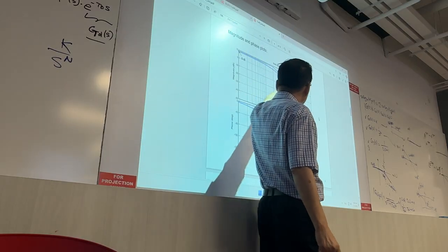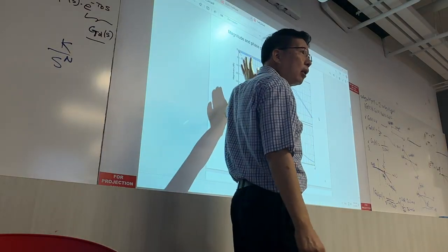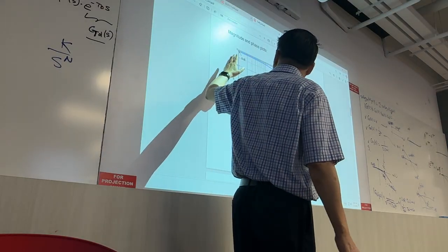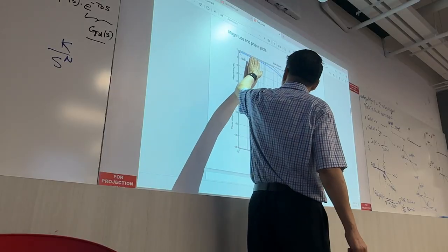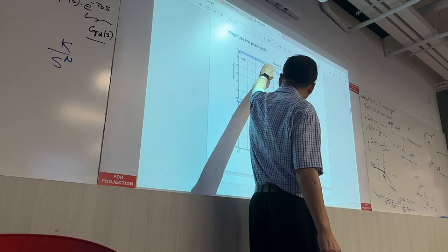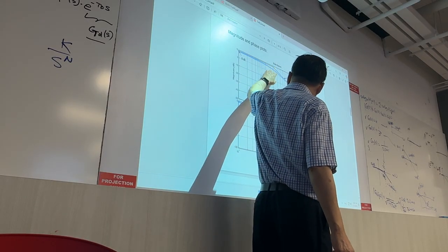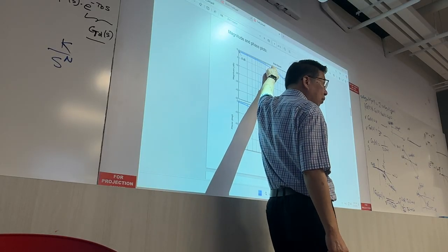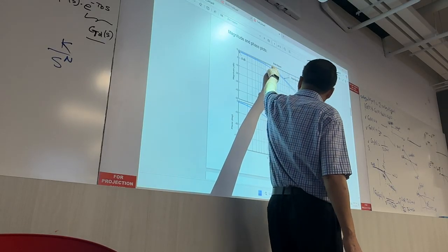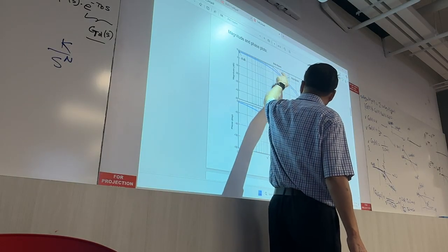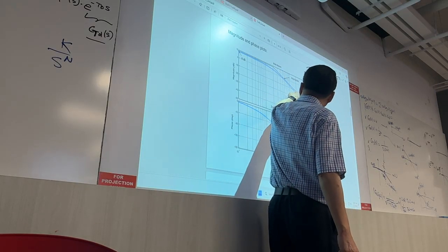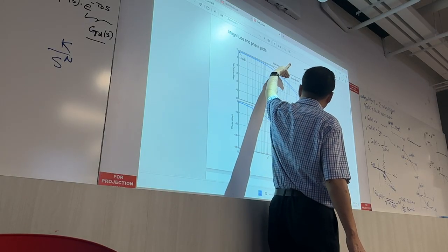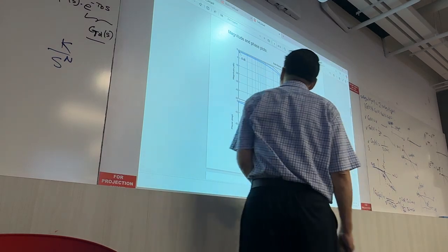The others do not come in yet. The others give you 0. Okay? So 8 decibels, all the way it will go until it hits the 2 radians per second. That is the first corner frequency. Over there we have 1 contribution from the denominator. So it bends downwards by 20 decibels.